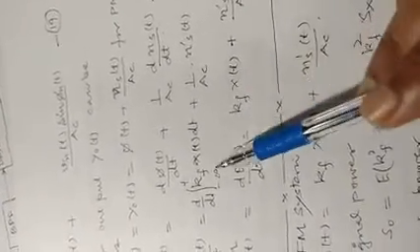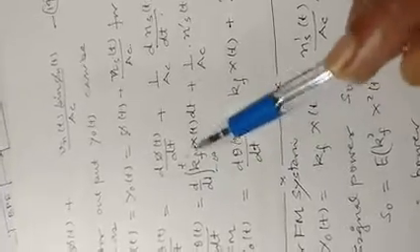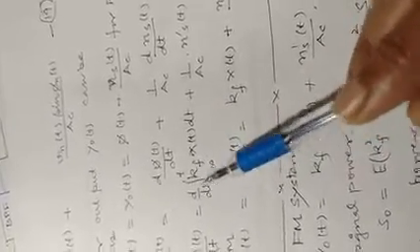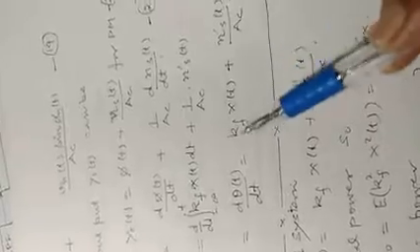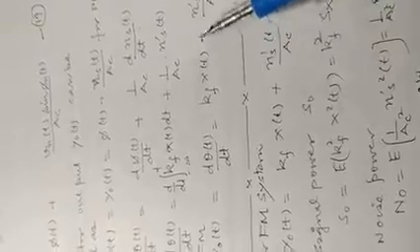frequency modulation system. So we have written y0 of t is equal to dθ/dt is equal to kf x of t. It will become this because the integral is compensated by that differentiation. So kf x of t it becomes, and n dash of t divided by Ac it becomes. Now we can calculate the noise power and the signal power in the FM system and PM system.